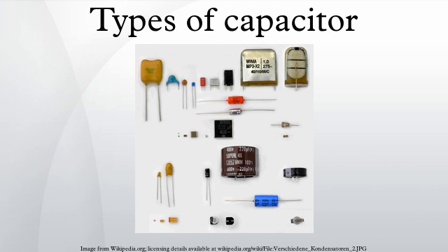The standardization of power capacitors, by contrast, emphasizes the safety of personnel and equipment, as given by the local regulating authority. As modern electronic equipment gained the capacity to handle power levels that were previously the exclusive domain of electrical power components, the distinction between the electronic and electrical power ratings blurred. Historically, the boundary between these two families was approximately at a reactive power of 200 volt-amps. Film power capacitors mostly use polypropylene film as the dielectric. Other types include metallized paper capacitors and mixed dielectric film capacitors with polypropylene dielectrics.